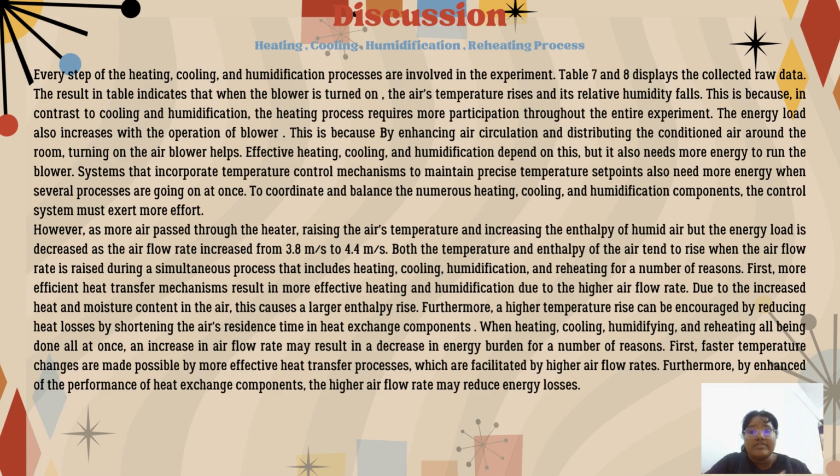First, a more efficient heat transfer mechanism results in more effective heating and humidification due to the higher airflow rate. Due to the increased heat and moisture content in the air, this causes a larger enthalpy rise. Furthermore, a higher temperature rise can be encouraged by reducing heat losses by shortening the air's residence time in the heat exchange components due to the increased airflow rate.